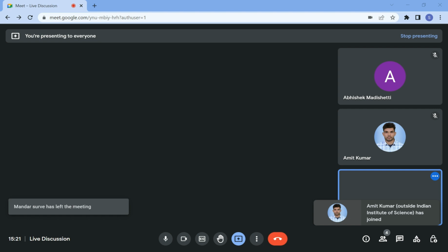So if you have in mind that final drawing that we usually have after rotating the lines with respect to HP and VP, then this apparent angle is visible in the drawing. So this will be 50, and this front view measures 55 mm, while its top view is 60 degrees inclined to the XY. So again, this is the angle that we see here. But are these angles the actual angles? Are these the true angles?